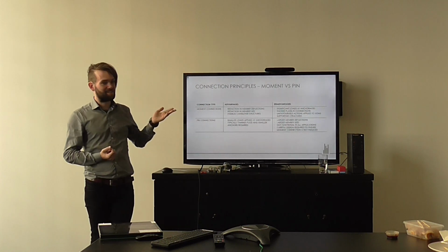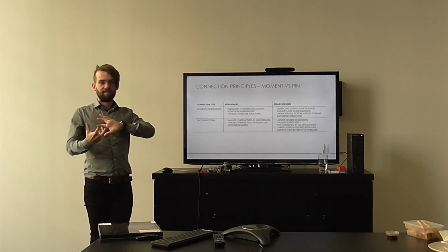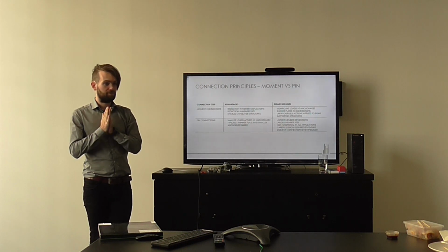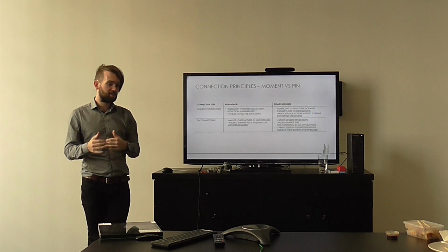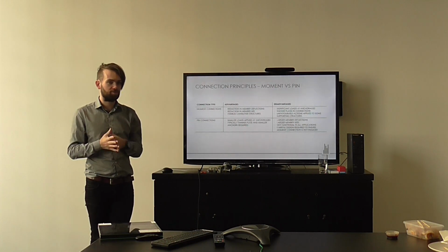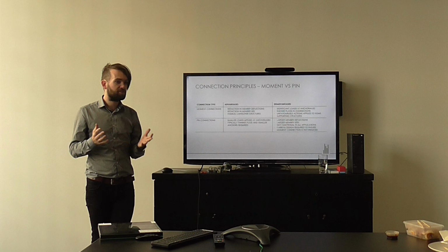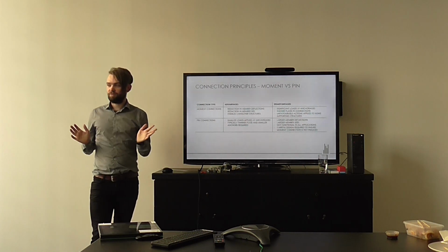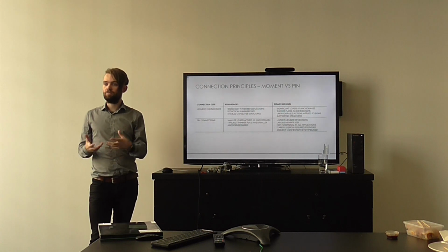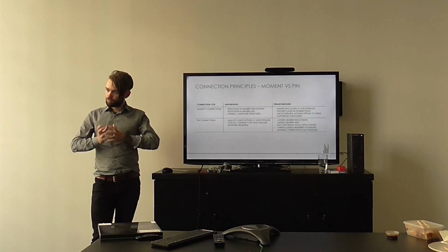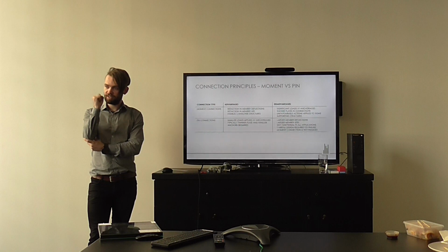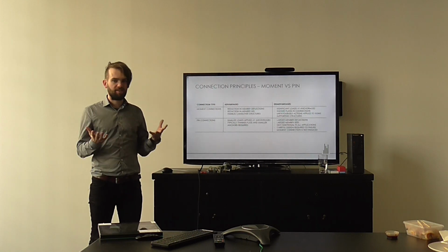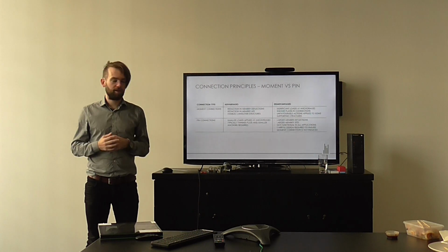Some of the disadvantages of this are that the loads that end up being applied at the base are quite significant, and they can be very significant for the anchors that we need to hold into the structure, whether it be a slab or a steel beam. At the same time, in some situations, they may not even be possible. The structure holding it might not be able to deal with the rotation force that the cantilever provides. So those are some of the disadvantages, and obviously you usually need thicker plate and more anchors.